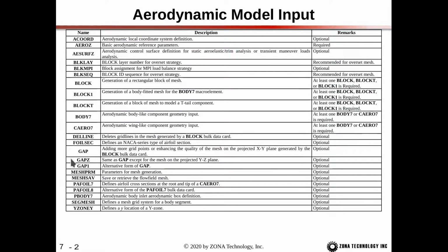We have the GAPZ and GAP1 cards to help set up the volume mesh. They function similar to an AEROZ7, except it does not define a surface mesh of the model. It just helps with the volume mesh generation. And then we'll go through the remaining cards as we come to them.